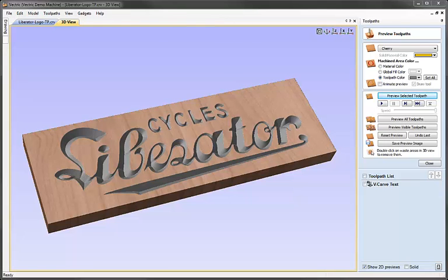In this example we've looked at the process to go from an image to a machine part. You've seen how we can take what was a fairly low quality graphic, import that into the software, resize it, and then use the specialty tool to fit vectors to the outlines of colours within that image. Once we created those vectors, we're able to go across and quickly calculate and save a V-carving toolpath, which we would then be able to take to the CNC machine and cut.